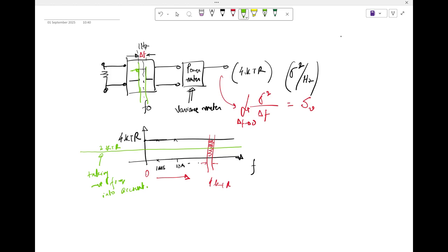And if you are splitting up your signal in Fourier series coefficients, which have a negative frequency component, then in order to do justice to how the noise is also getting affected, you have to take into account the negative frequency of the noise also, right? So we'll talk about this when we come to LPTV systems in more detail. But the thing is, this can sometimes lead to mathematical discrepancy: if you do your analysis using 4 kTr or you do your analysis in 2 kTr, you might not get similar results. If you do not, then you go back and check whether this assumption that you have taken is valid or not.